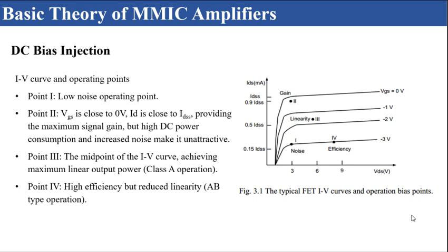Transistors require DC bias to operate. Set the operating point to display ID-VDS characteristics, and the AC microwave signal fluctuates up and down at this value. And I will introduce the ID-VDS curve and operating points in detail.